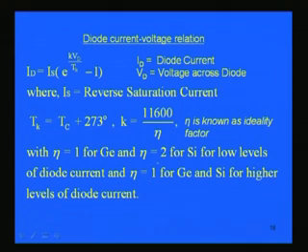So, the diode current ID bears a relationship with the voltage given by this equation. Is is the reverse saturation current which we have discussed, and the Kelvin temperature Tk is given by the centigrade temperature plus 273. This is Kelvin, mind it, it is not centigrade. This relationship is helpful in finding out the characteristic of current versus applied voltage in a diode.